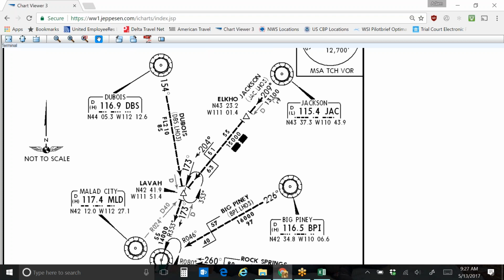That basically means that as they start looking at the chart, they're supposed to not only follow this track here, but they're also supposed to maintain the altitude that it says on the chart. And that means they're cleared to do that without ATC telling them that they can do that. So when they give them the clearance, you are cleared to descend via the Brigham City 3 arrival, that means you're cleared to follow every instruction on the star as it's prescribed on the star.